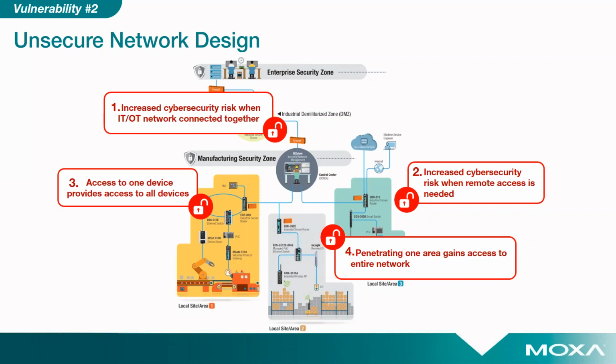So you want to be able to have things in place like, let's say, a firewall that can block anything from going into the device that's not Modbus traffic, like I mentioned earlier. Or maybe you only want read access to that. You don't want it to be able to write to one of the coils. It's important. It's important to make sure that all the security is in place.